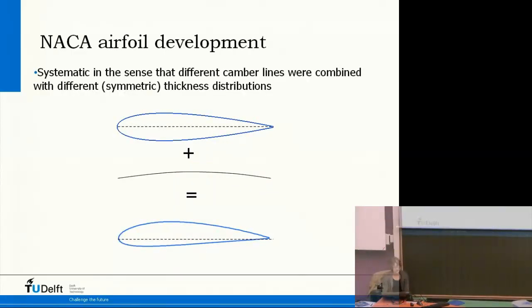Now, airfoils. There's a very famous series, the NACA airfoil series, and these are developed with specific characteristics. Of course, you can start with a symmetric airfoil. Then, what you typically can change is the thickness. So you have a maximum thickness parameter that is important for the properties of your airfoil. So maximum thickness is typically reported. So the NACA 0012 is non-cambered, 0, and the maximum thickness is 12% of the chord. You express that typically in percentage of the chord.